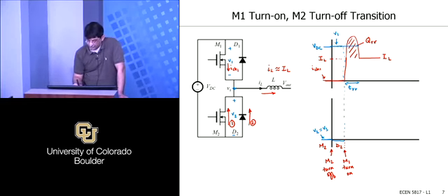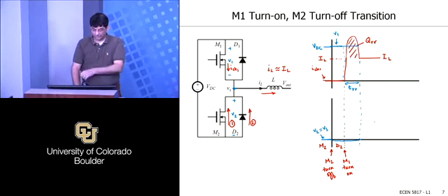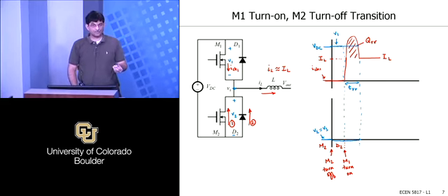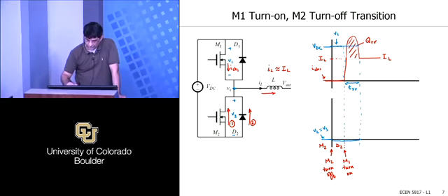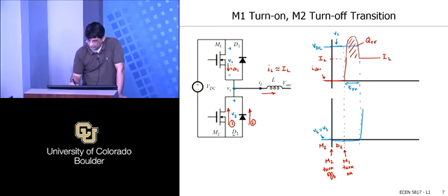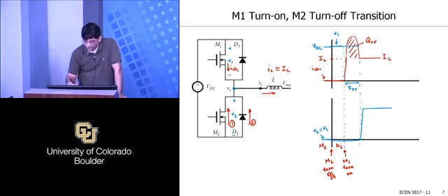So throughout this period we have essentially the diode conducting, and then the diode voltage can go up. And I'm going to make an assumption for this that it's a snappy diode. What a snappy diode basically means is that once all the charge is removed, it just snaps back up and blocks voltage immediately, all right? So in the snappy diode, the voltage will just quickly come up to the VDC level like that, and soften that corner.